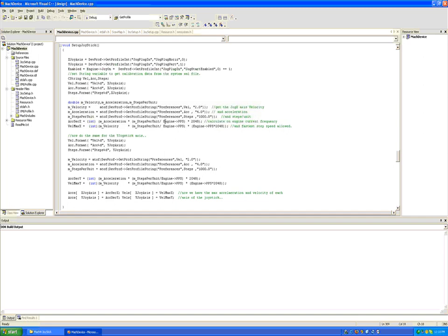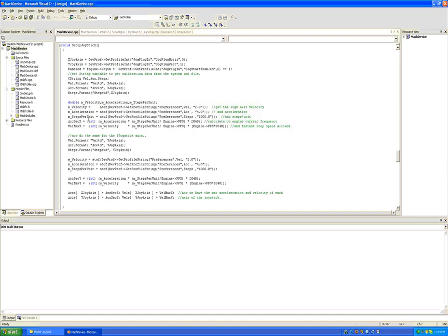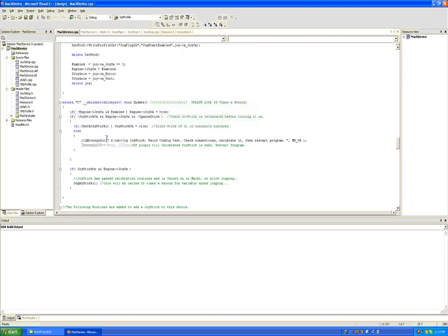You'll notice I divide by one of my engine variables, PPS, which is pulses per second. In order to calculate a proper acceleration, I have to know what speed the engine is going, other than just number of steps per time. So I divide by engine pulse per second, and there's a magic number, 2048, that I multiply by simply to give myself a double-digit precision of an integer in the engine when I'm actually doing accelerations. Again, I realize that's gobbledygook to most of you at the moment, but you'll figure it out as you go and begin to play with accelerations and so on. So setting up the joystick only takes about 15 lines, and all I'm doing is remembering accelerations and velocities.